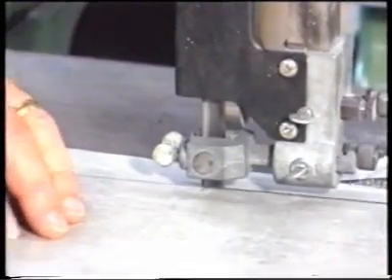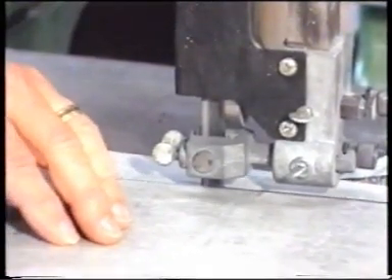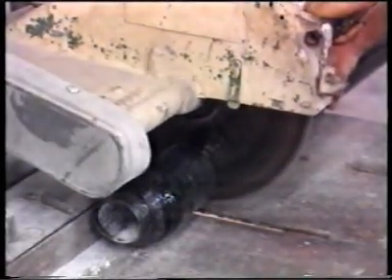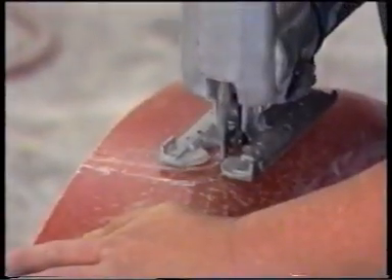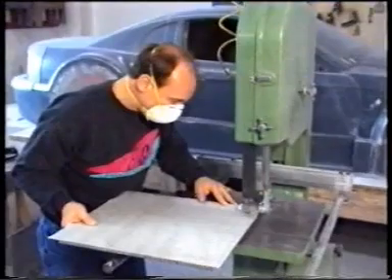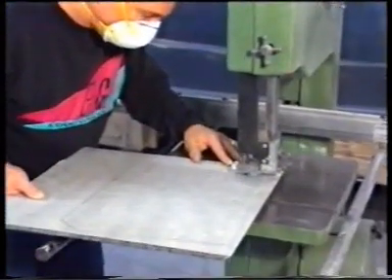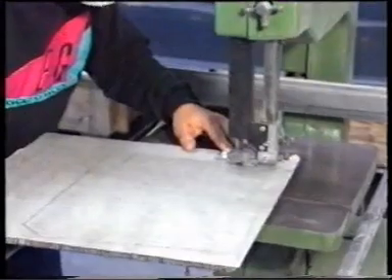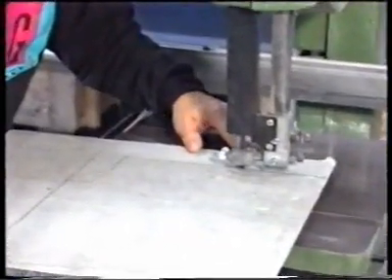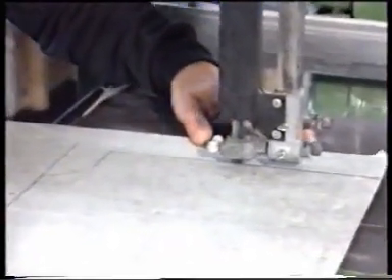Polymer matrix composites are typically cut with bandsaws, circular saws, and saber saws. Bandsawing speeds with high-speed steel blades range from 4,000 to 6,500 feet per minute at feeds of 6 to 12 inches per minute.